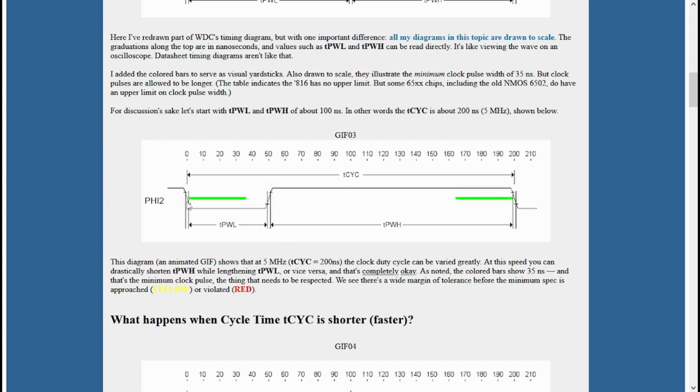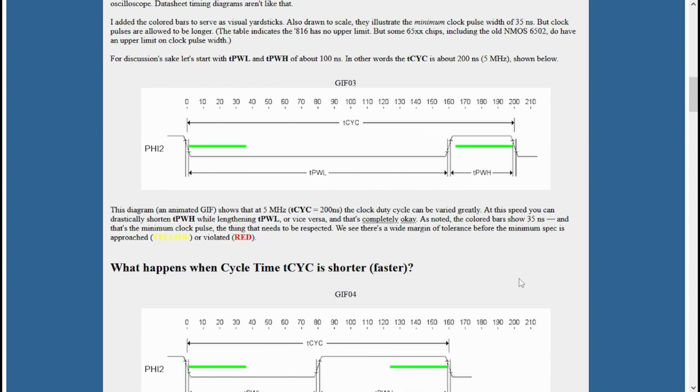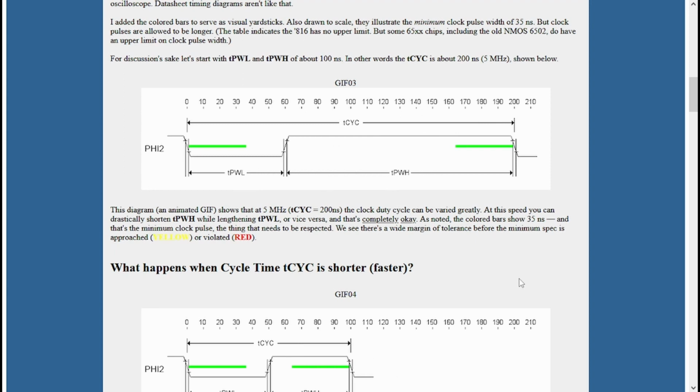And it's probably gonna be around that period here, which in this case is saying around 350 nanoseconds. And so if our frequency or period is encroaching on that area, we're not going to be able to get anything sensible out of it. And we'll have a look at the implications on that when we increase the speed on our version. So take a look at this website. It's really useful to understand the various aspects of timing on these CPUs.